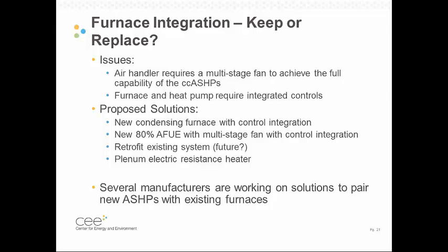Another option that we get into in the full report, and I'll only briefly mention here today just for time reasons, is eliminating the furnace and going with just a plenum heater as backup. As these heat pumps work at colder and colder temperatures, maybe there's less time where you're relying on backup at all, and you can get away with just a boost in performance. So the heat pump would still run always, and the plenum heater could just give you those extra BTUs or extra degrees of temperature that you need, as opposed to having a full furnace backup. That's a potential option, especially in small, tight houses that don't have as big of a heating load.